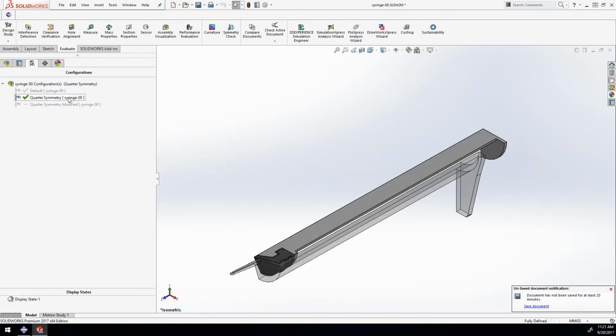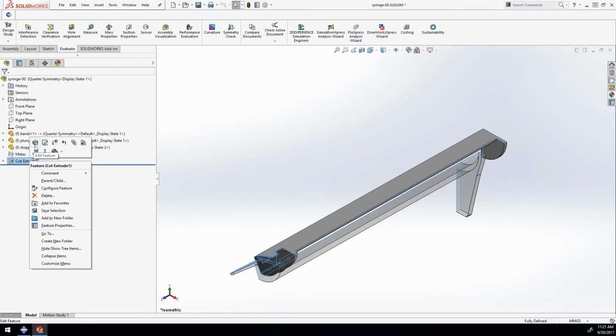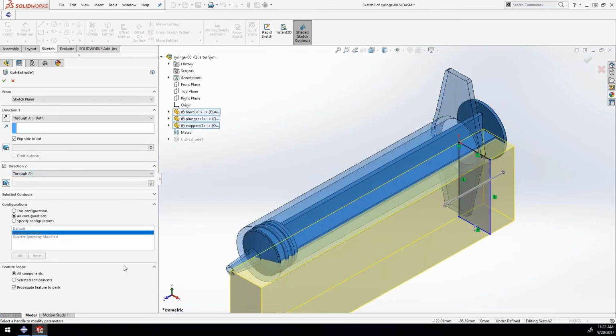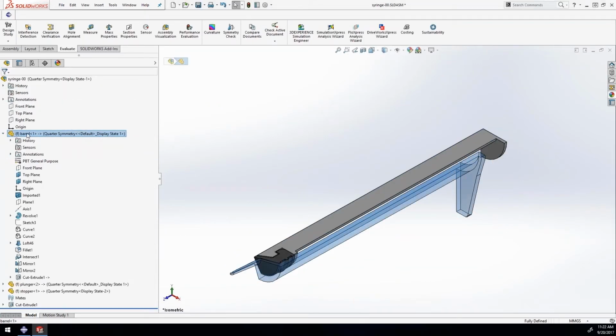And so we've got this set up already in a preset configuration, and we made that just with an assembly cut here. If we take a look at that, that brings us to the first thing I wanted to point out about the associative interface, which is this propagate features to parts option down here. We check this on, and what checking this on does is create a feature at the part level that's going to change the part itself.